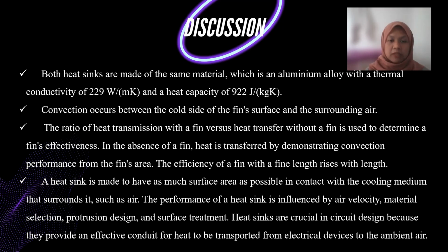The performance of a heatsink is influenced by air velocity, material selection, protrusion design, and surface treatment. Heatsinks are crucial in circuit design because they provide an effective conduit for heat to be transported from an electrical device to the ambient temperature.